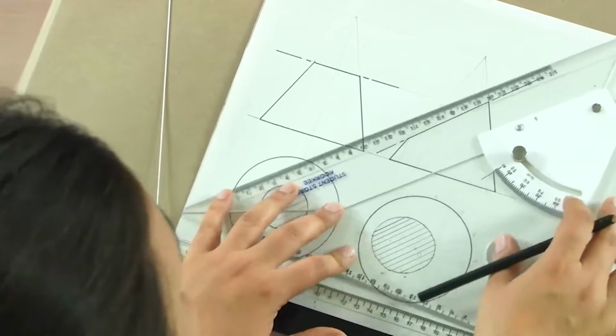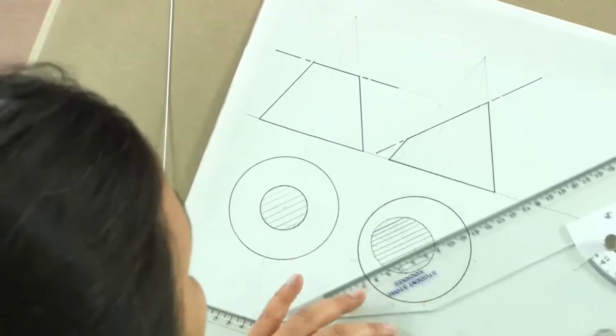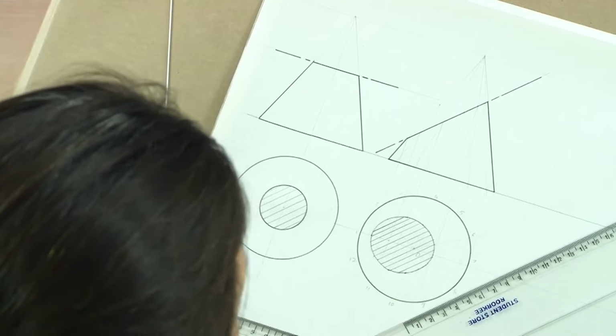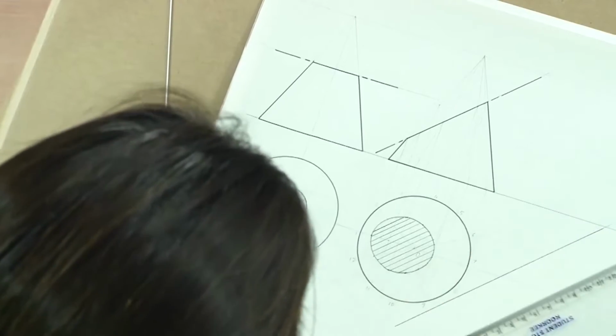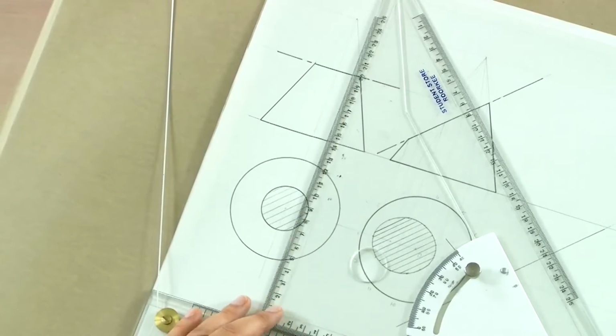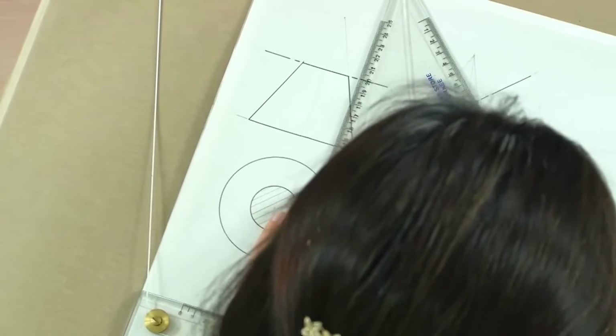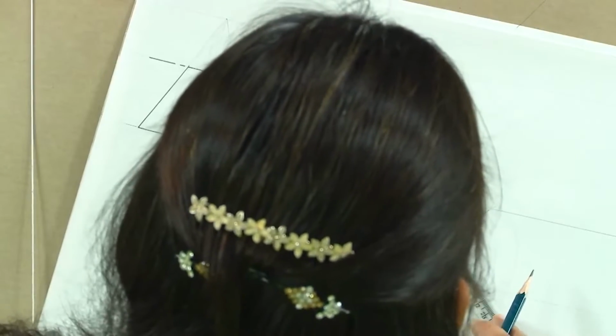So we can draw an auxiliary plane which is parallel to the section plane, which is what I have taken this side because there is no space. However, you could take it there, wherever it is convenient. The only thing is it has to be parallel, and all we are going to do is bring back the projectors for the generators. So, all I am doing is bringing back the projectors of the generators here.